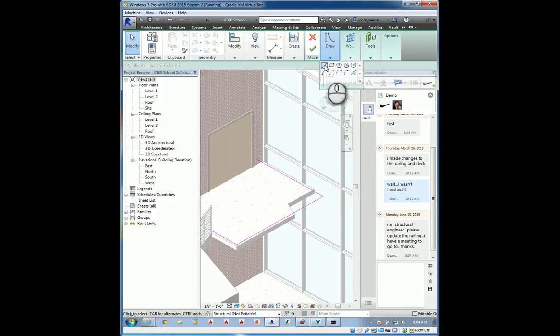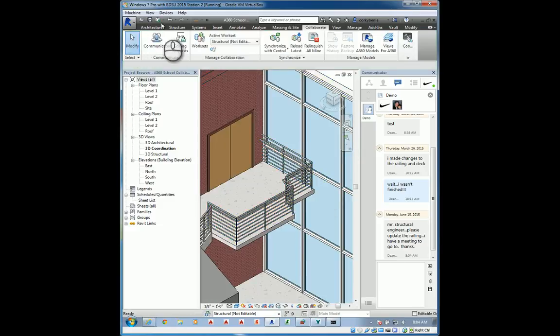I'll go over here and I will draw, well, let's use a pick method with, say, a 3-inch offset. And we'll clean this up, and we'll finish it. Now the information is updated. I'll save it. I'll save it back to the central model. And as you can see here, there's information that's being updated.